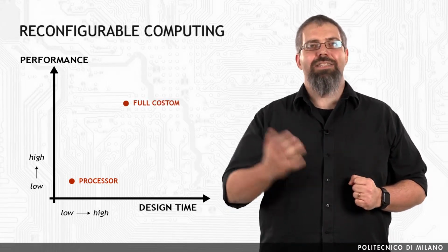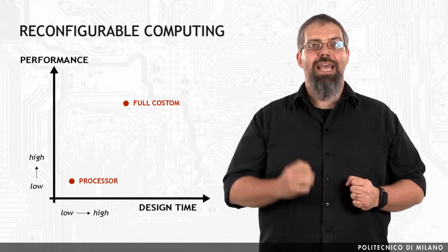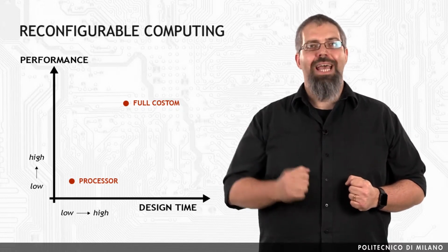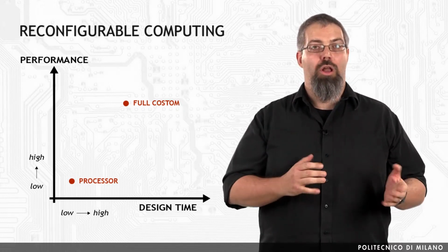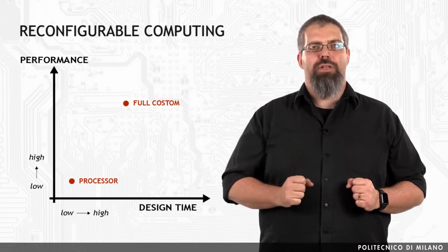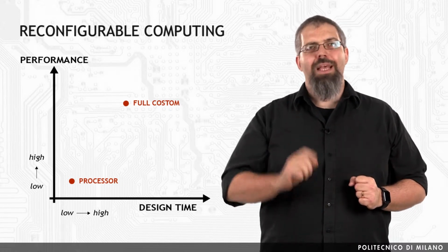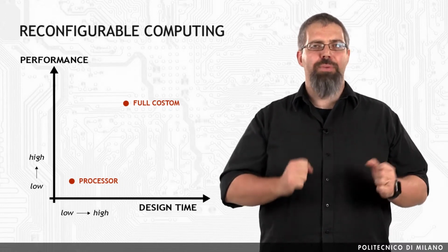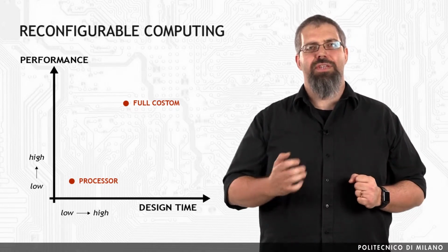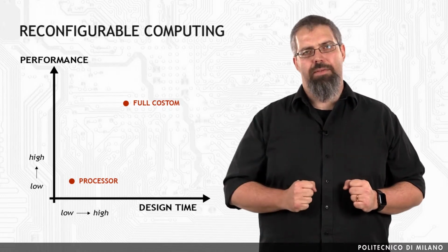An ASIC is an integrated circuit specifically designed to provide unique functions. ASIC chips can replace general-purpose commercial logic chips and integrate several function or logic control blocks into one single chip, lowering manufacturing cost and simplifying circuit board design. Although the ASIC has the advantages of high performance and low power, its fixed resource and algorithm architecture results in drawbacks such as high fabrication cost and poor flexibility.